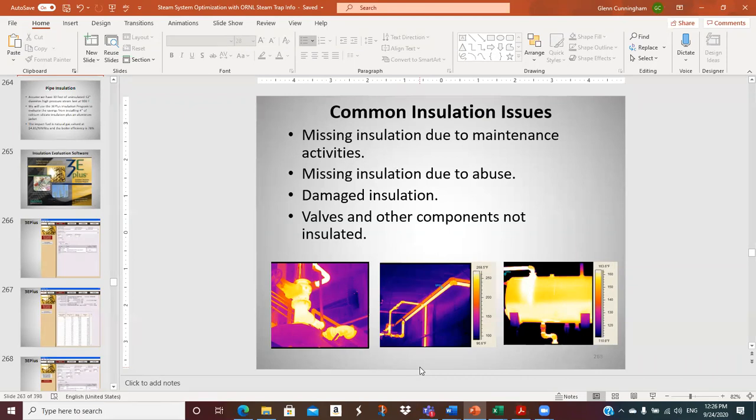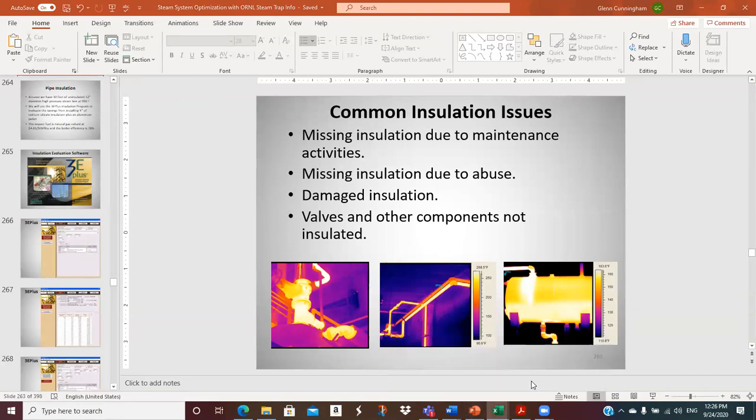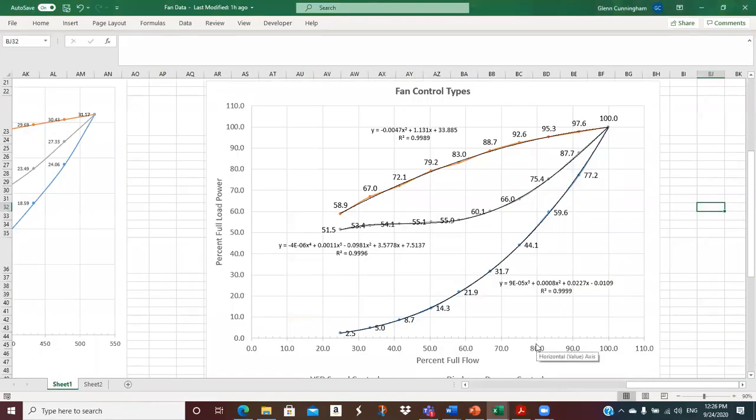But if you just ratio the steam flows, you would say 70%. So that would mean my fan would be operating at roughly 70%. And this is steady state, so it's 70% all of the time. Okay? Well, one thing you can do is use these curves if you had them.